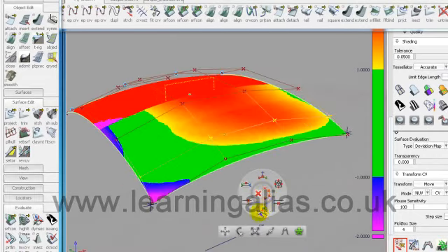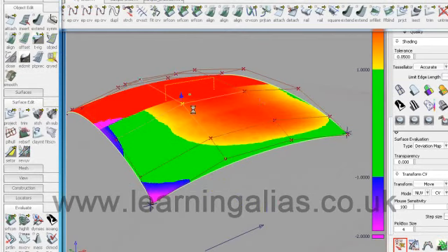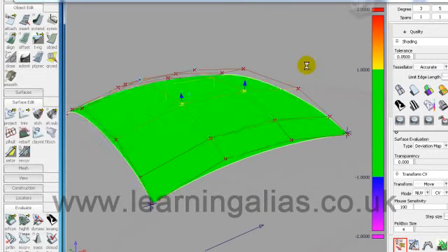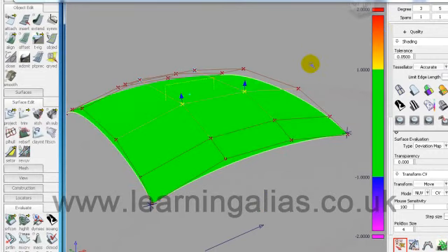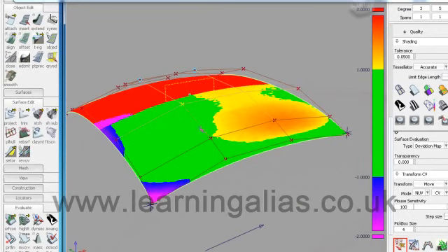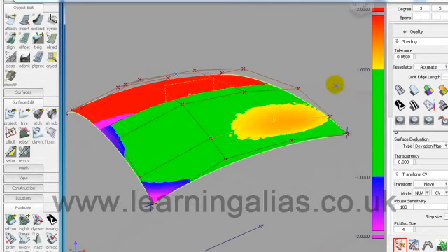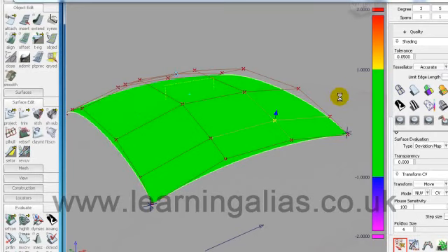Now go back into F8, individual CVs in NUV, and we can see that those two CVs there are red. I'll bring it down just a touch. I'm using the mouse because it's a long way away, and as soon as we get to that condition, I don't need that CV active, so just select one CV and a little touch there, and then when I get very close, I've got the option of using the nudge key.